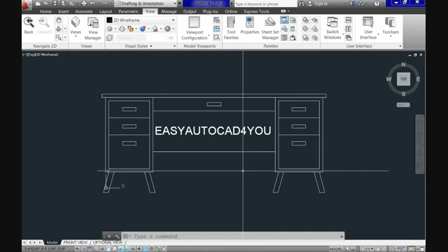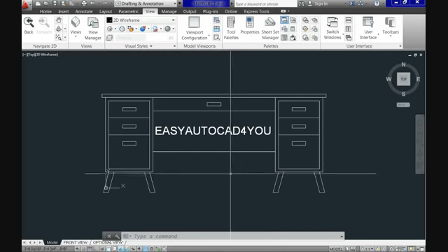And let's wrap up the template concept. A template is a set of preset instructions and characteristics for boosting your productivity. In AutoCAD, typically a template includes units and limits, layers with line standards, text, dimension, leaders, tables, plot styles, common symbols and blocks, the title blocks, and several other specifications.